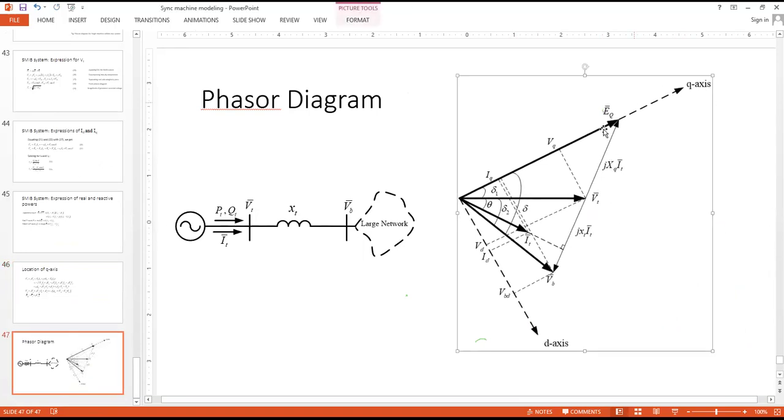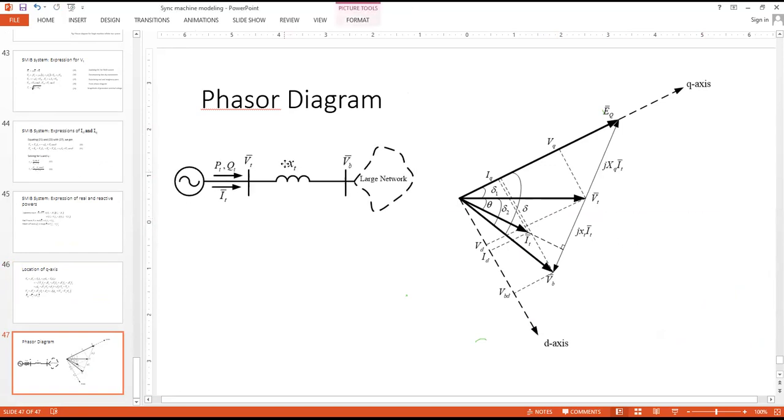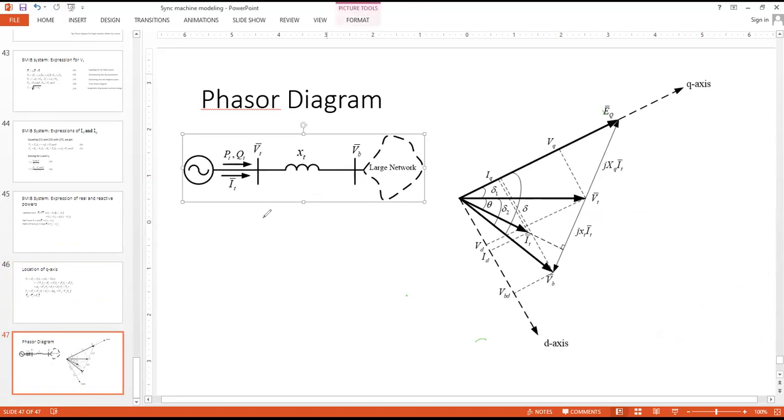Can you understand clearly what is written on the right within the block? Okay, so let's start. In general, to find out the initial operating point or the initial operating condition, you need to know at least some values related to the network. Those values should be given, or you should be able to calculate them beforehand. For a very large network, we generally take help of load flow analysis to know these values at each bus. But for this system, we will assume that these values are given.